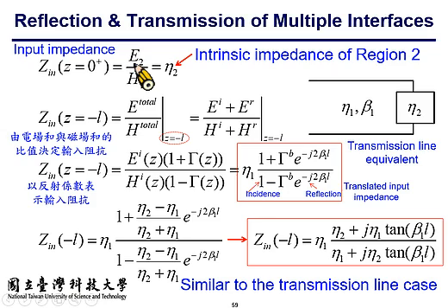And you can do the same for the H field, but you need to use the so-called current reflection coefficient. You need to be aware that the reflected H field is inverted at the boundary, so you have the minus sign over there.